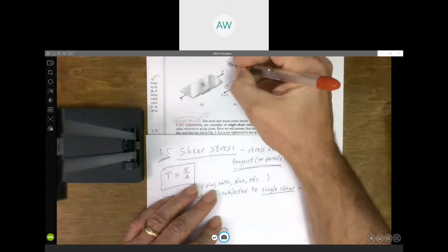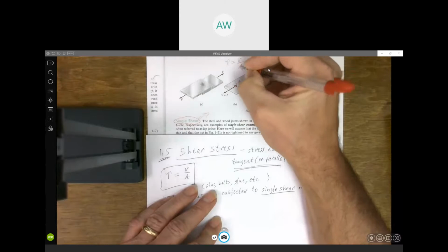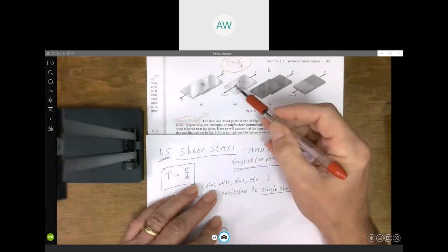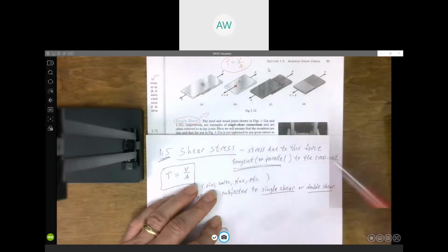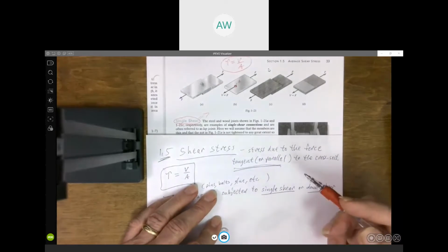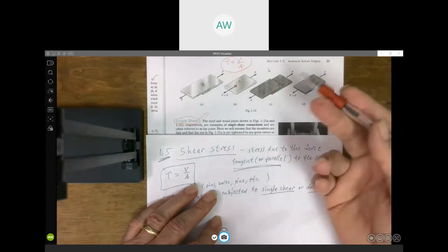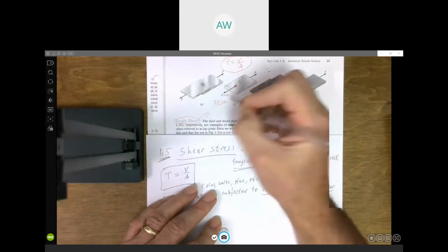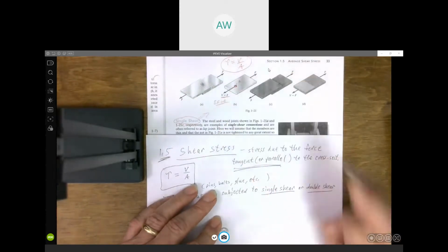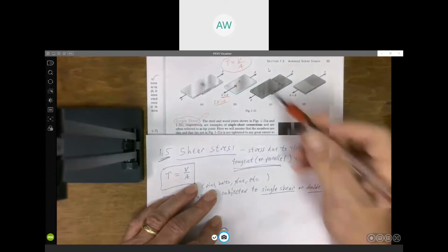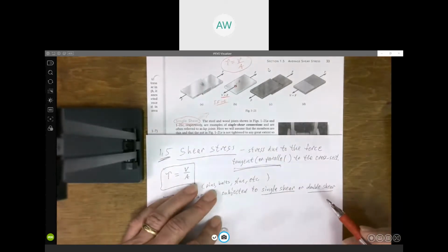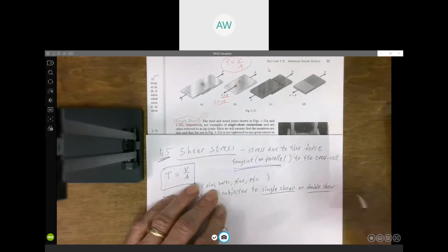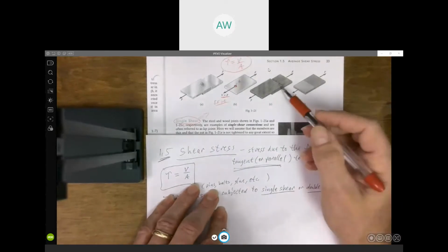And so what you're looking at here, when you're doing tau is equal to V over A, the area A is the cross-sectional area of that bolt. And due to equilibrium, right, the sum of the forces has got to be equal to 0. Right, shear force V has got to be equal to whatever that applied force F is. So the same thing would apply here.